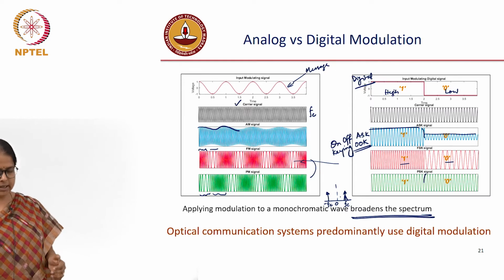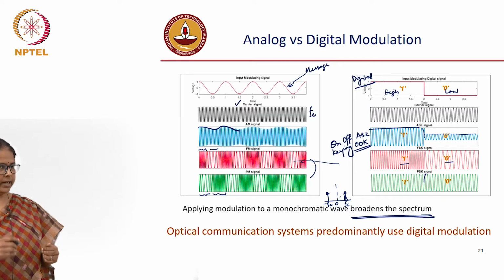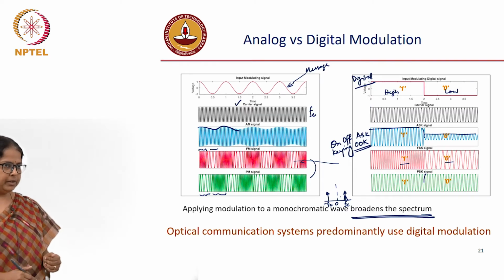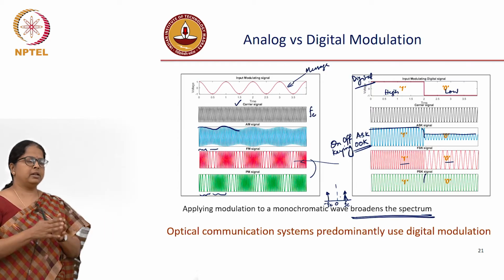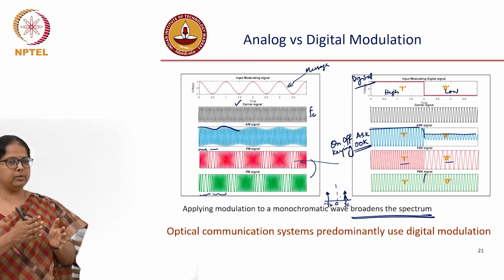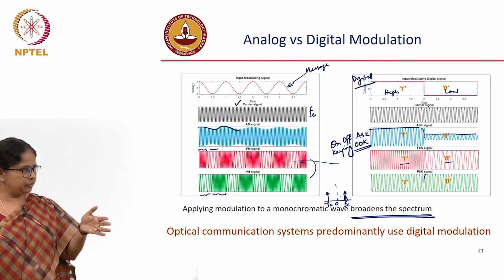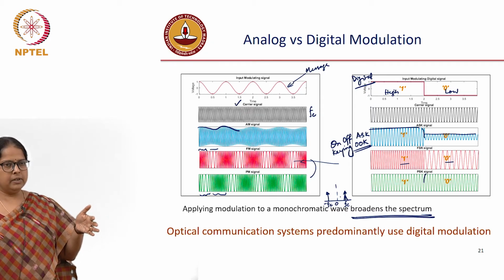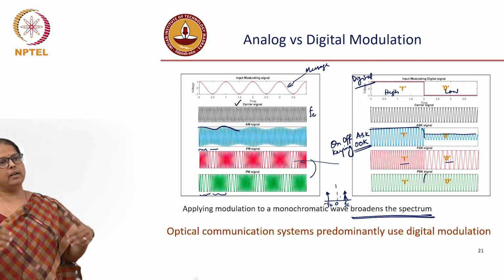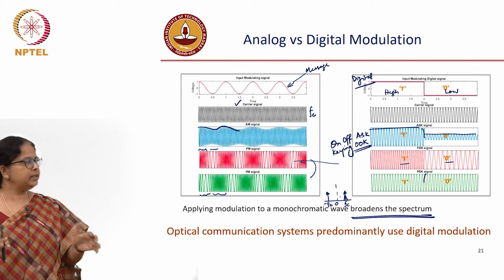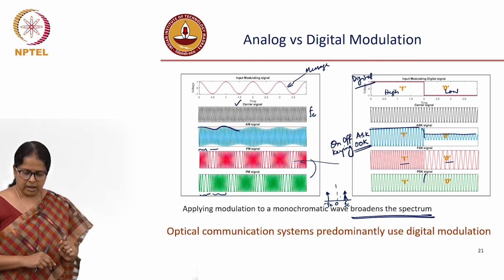So, that is why I am saying that applying modulation, this idea, you will need it later. It is no more just the carrier frequency, it is no more the line width or the frequency width of the carrier, it is the width of your entire signal, which is decided by the bandwidth of your original modulating signal. Okay.